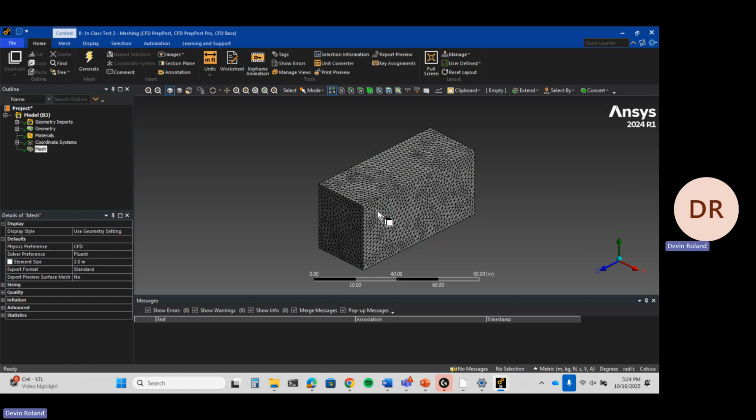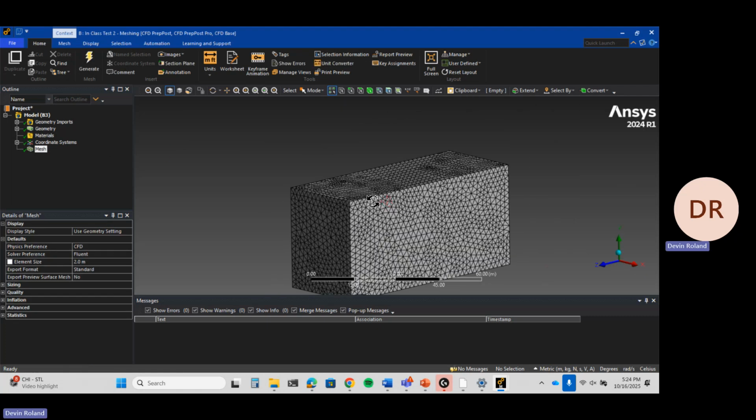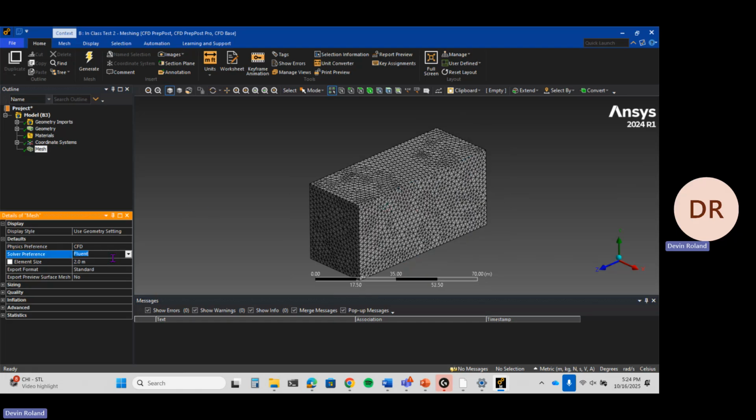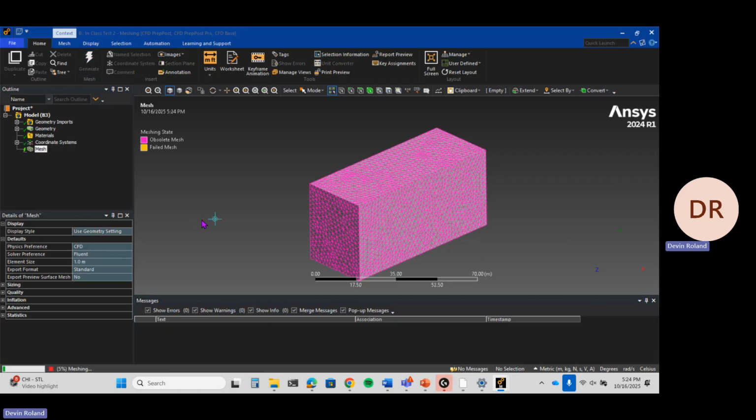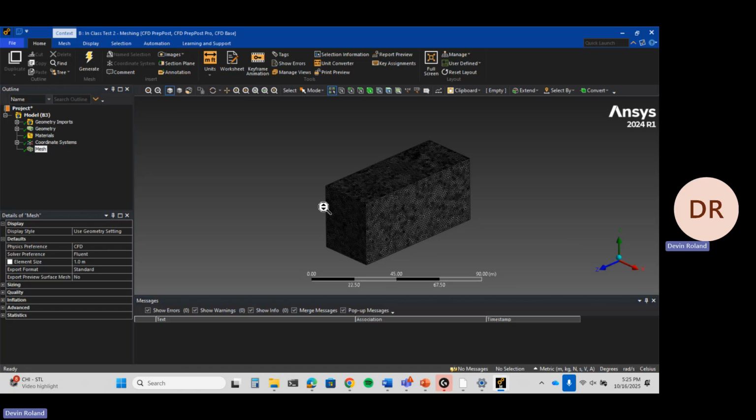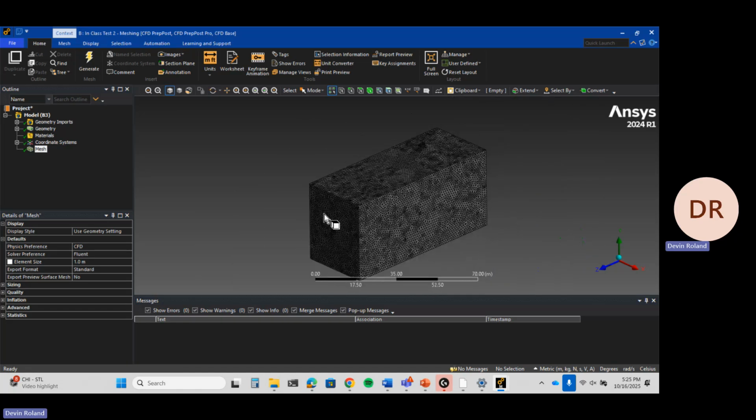All right, nice. So that's still maybe a little bit more choppy than I want. Let's do 1. I think 1 might be better. Okay, yeah. Okay, there we go. That's good enough. So we have this now. I'm not going to do anything special like refinements on this. I'm just going to leave it with this pretty fine mesh. But if you wanted to go in and refine around the trailer, that could be good if you were doing an actual scientific case.